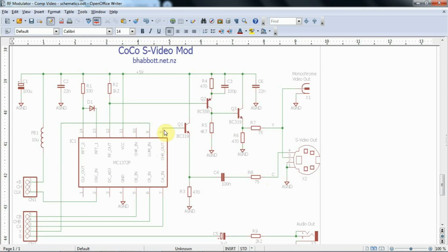Remember, we saw that pin 8 is the combination of the channel A color, the A reference color and the B color. That's output on pin 8. And if you don't feed that back into pin 10, or even if you do, you can take off of pin 8 and buffer it with an emitter follower, and then send that out to the chrominance pin on the S-Video.